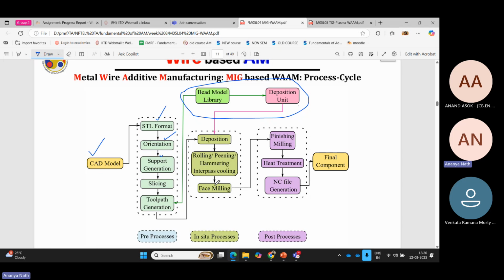The heat will still be there because of the conduction of heat, but you can start the process after 5-10 minutes because there is a continuous flow of argon gas, which is also helping the bead to cool down. No, if it is polymer additive manufacturing, then it will be okay. But here, it is almost welding, so the rod will be heated up.